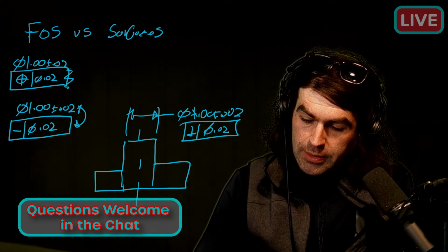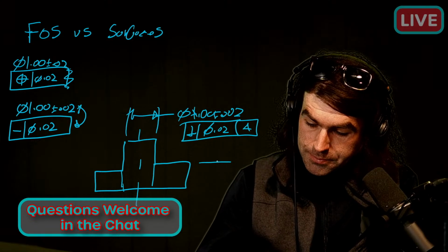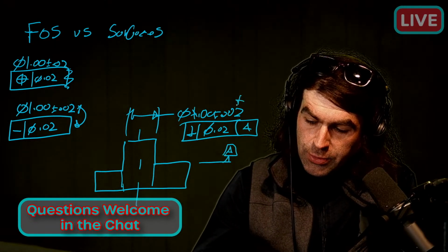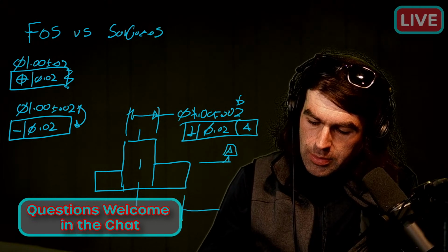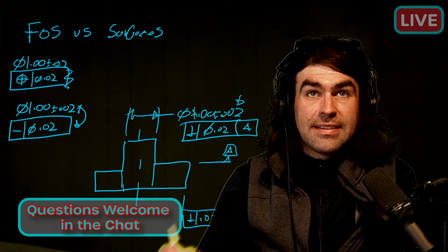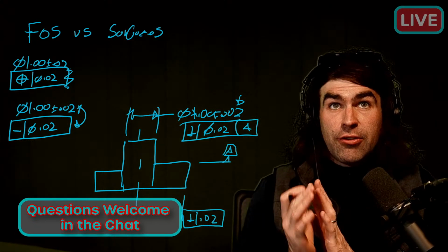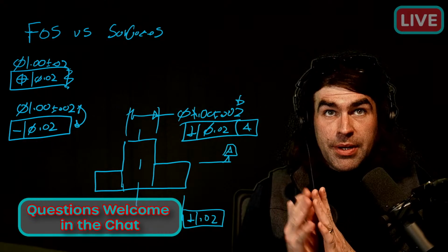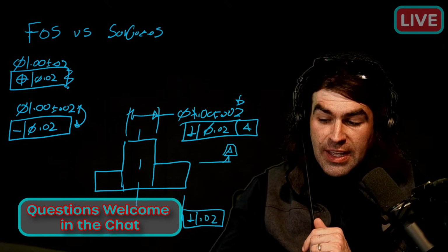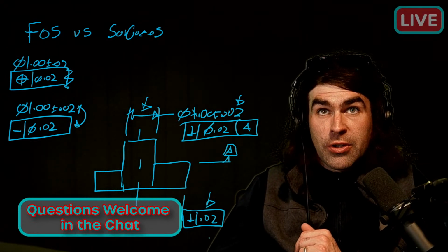We would put the perpendicularity tolerance next to that dimension, but say the side of this part is perpendicular. It doesn't go with the dimension. It's a totally separate thing. And that's done for a reason. It's just an extra step in making sure something is applying to, in this case, the axis. This one is applying to the surface based on where the feature control frame is.